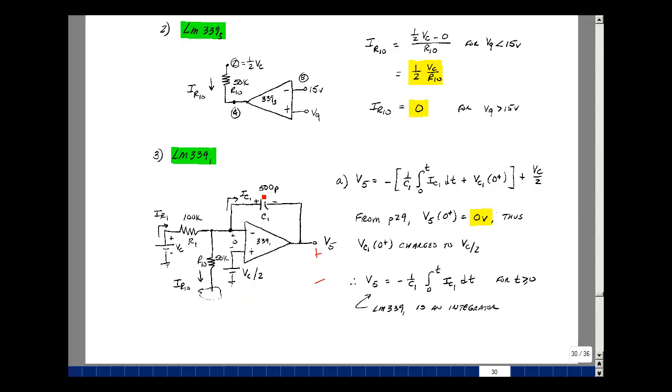Well, when I ran the simulation, I didn't use the command on the .tran line called UIC, which is user initial condition. When you don't specify that, the program open circuits all capacitors and short circuits all inductors, although we don't have any. It finds the initial condition. If you put the UIC letters at the end of .tran, it will treat a capacitor with no specified initial condition as 0. Well, let's just figure out what that initial condition must have been.